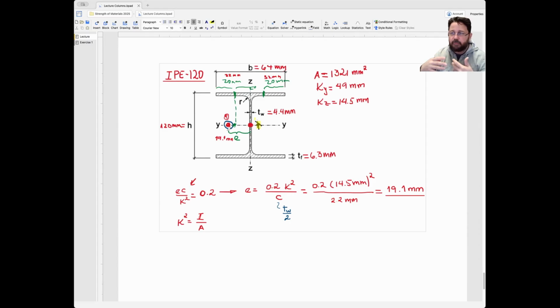Then you can calculate, for example, how much is that. Meaning that even though your assembly process is not perfect, you could estimate or use safety against that. And that's the reason for these considerations, because you're not going to escape from using eccentric loading. So if you're not going to escape, okay, let's quantify the magnitude of things.